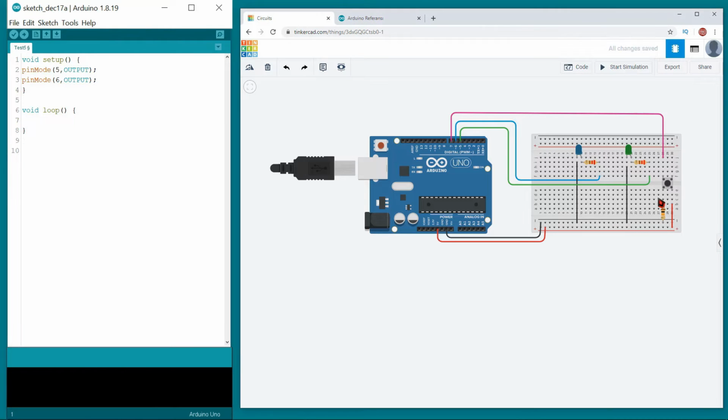Upon examining the button state, we observe that a 5-volt voltage is being transmitted to the button through the breadboard. Pressing the button results in the 5-volt output reaching pin 7, and when the button is not pressed, 0 volts, indicating no voltage, is present at the pin. At this point, our primary concern is the condition of pin 7, not the operation of the button. Since pin 7 facilitates the flow of information from the outside to the Arduino board, we need to define this pin as an input. Now, let's define pin 7 using the pinMode command. Write pinMode 7 input. By doing so, we have defined that pin 7 will be used as an input.